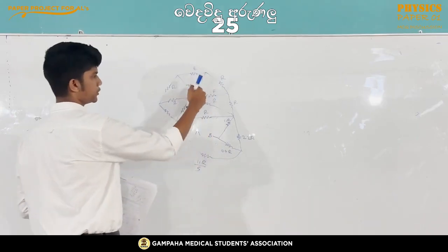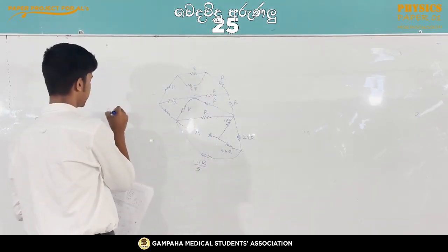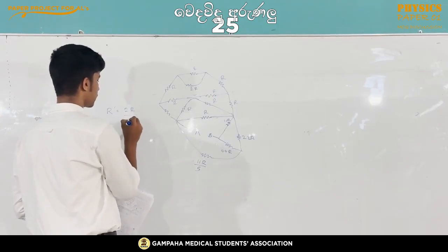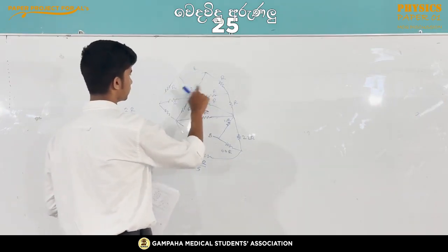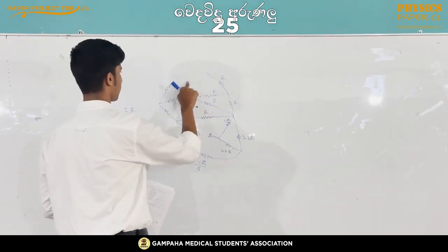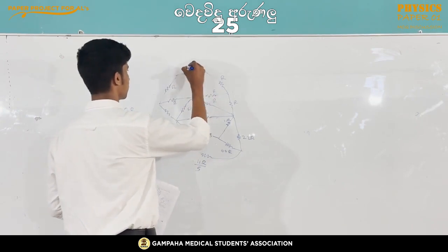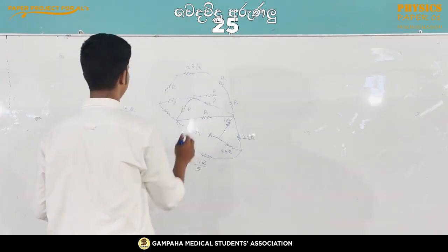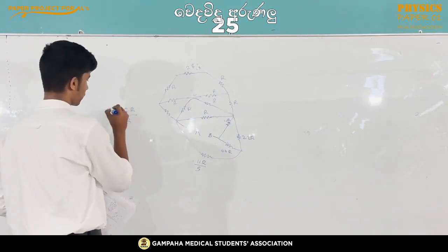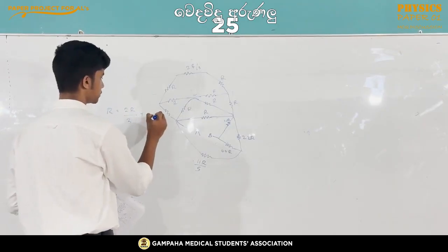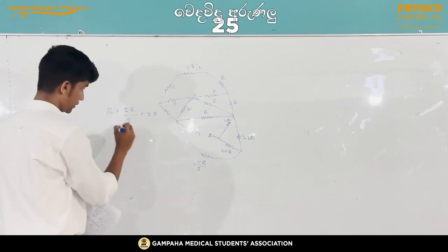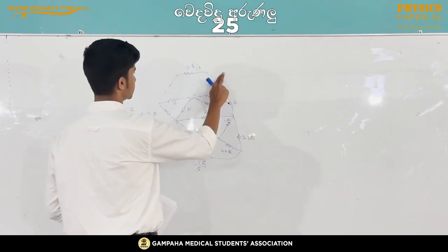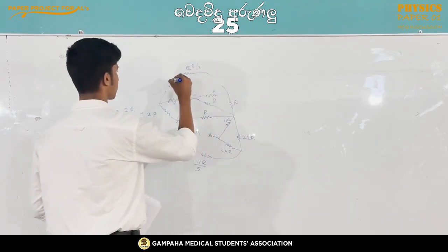Then the resultant of these two resistors, when we use the product over sum method, will be 2R over 3. So then the resultant of these two is 2R over 3. And once again, these three resistors are in parallel, then we can add 2R over 3 plus 2R. Then the addition will be 8R over 3. So instead of these three resistors, we can write 8R over 3.